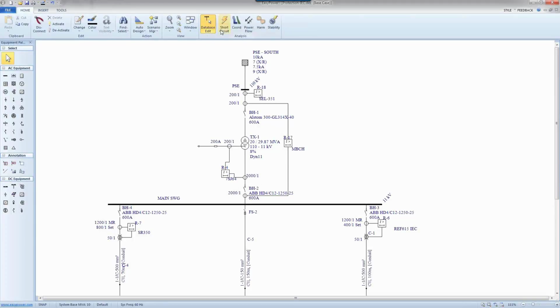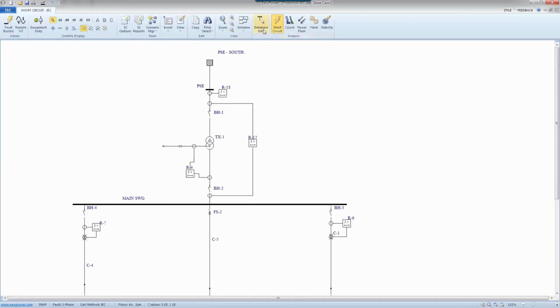I talked about different currents, so I switched to short circuit, and you would see the initial. You would notice the terminology that has changed here. 1, 2, 3, 4 type of breakings that have been added here, and a steady state. So this one becomes 20 millisecond, 50 millisecond, 100 millisecond, 250 millisecond, and a steady state. You would imagine, and it makes sense, that these are the breaking currents. So this is the initial.